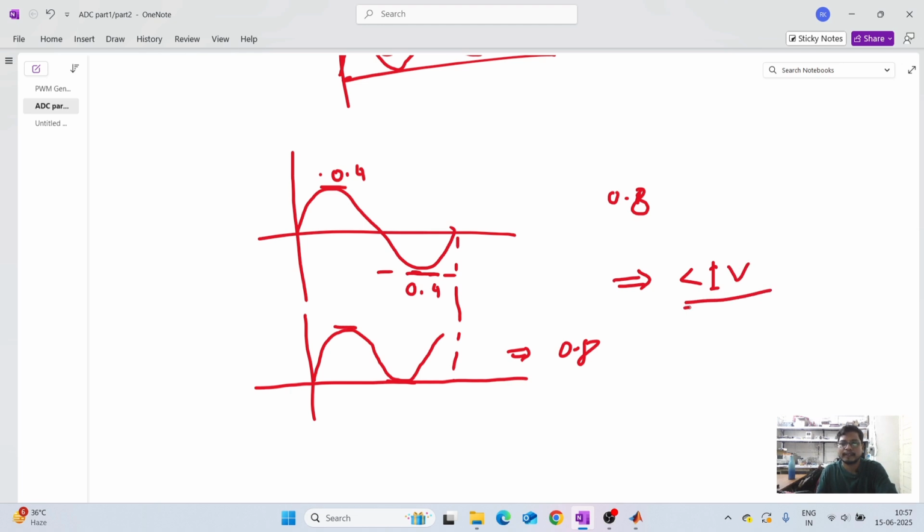If you give more than this, then your FPGA may get damaged. So for safety reasons I gave a voltage of 0.8 peak to peak. So what I have to do is add a DC signal to this sine wave to shift it above 0.